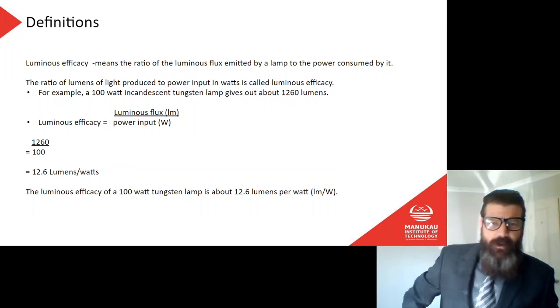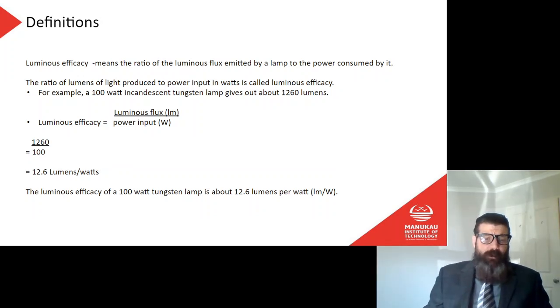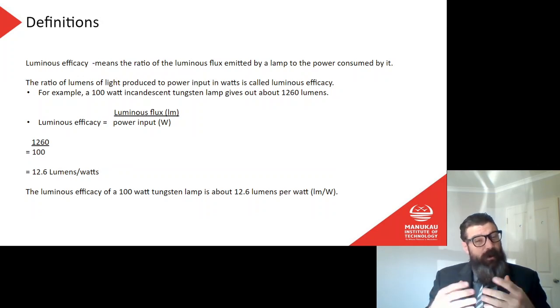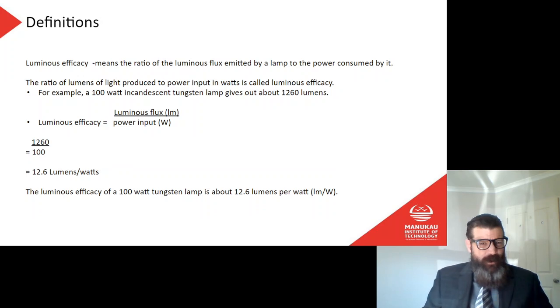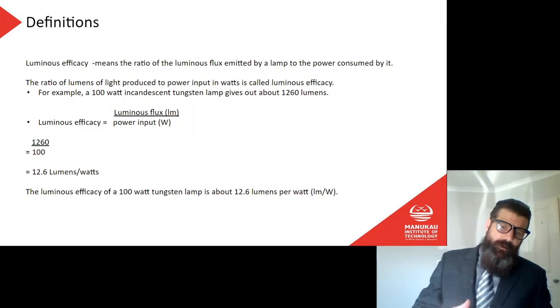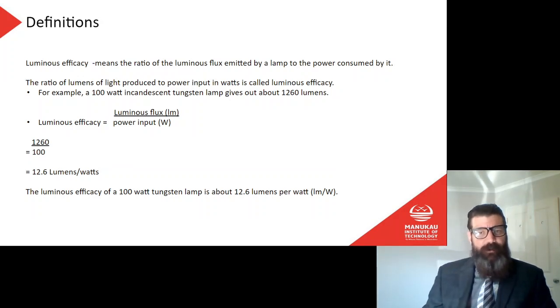Why is this important? Actually, it's really important. It's incredibly important to be able to measure the luminous flux per watt. Why? Because it tells us how efficient that light is, how much light I'm going to get out for, and what is power input? Power input means how much it costs me. Remember that I pay for my watts, right? So a 100-watt lamp is going to cost me 10 times more to run than a 10-watt lamp. Will that be more efficient? Well, not if I need 10 times more lamps, then it's the same.